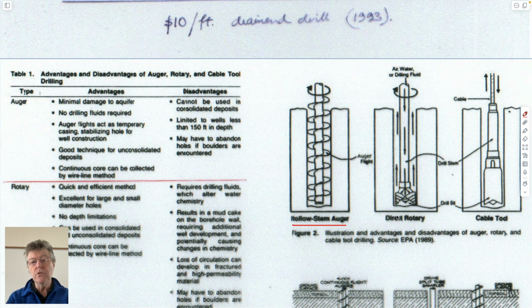If you're drilling in soil or rock, then direct rotary drilling is one way to do that, usually with a tricone bit. Drilling fluid gets flushed down the center. It could be air. And the cuttings, which are broken off from the base of the hole, get flushed up to the surface. Maybe they hit you in the head, or maybe you just collect them to be able to see what you're going through at a given depth. And you know how many drill rods you have to be able to say how deep you will be and how deep those samples are coming from.